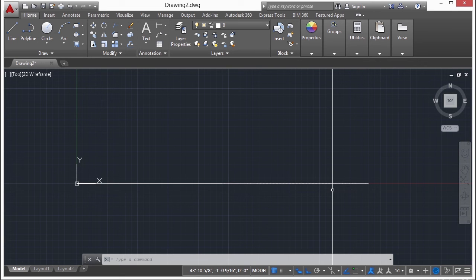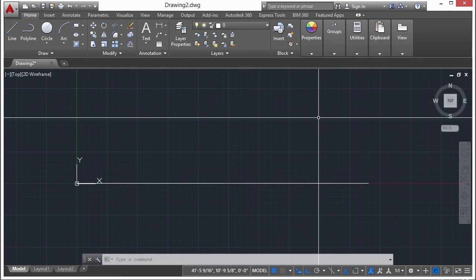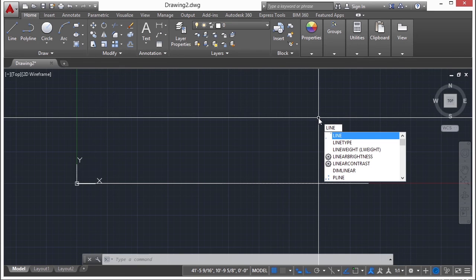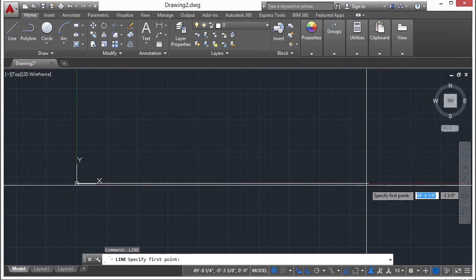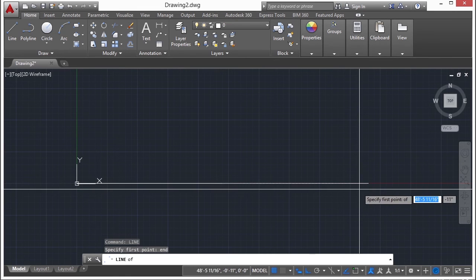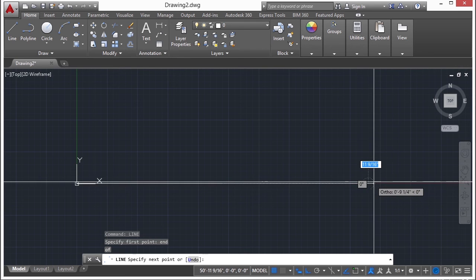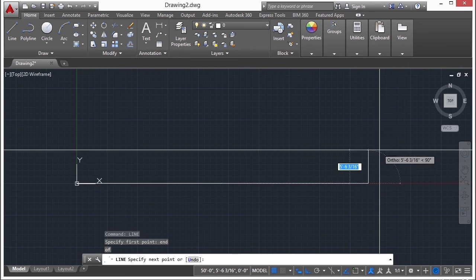Now we're going to draw our next line, and this will be sort of the side wall of our house. So start the line command again, press return, and we're going to draw it from this point right here. Well, if you type in the letters E and D for end, this will do an O snap override. Press enter, and it will snap. See that little green glyph that pops up there? That'll snap on, and that means it's locking into that end point of that line.